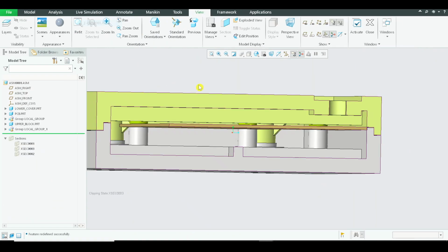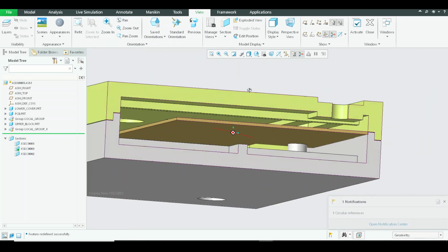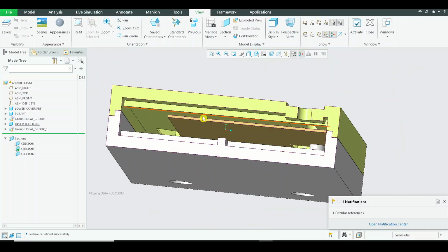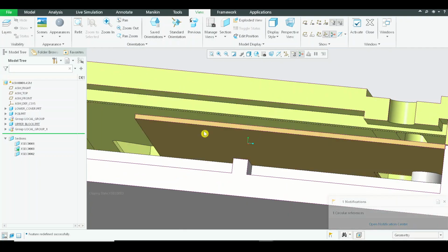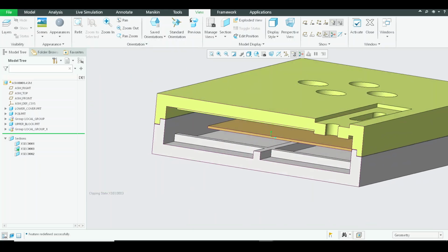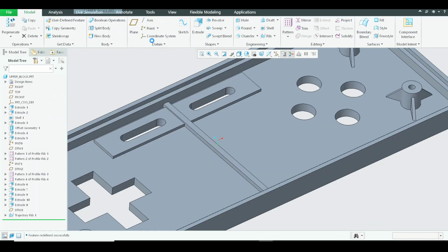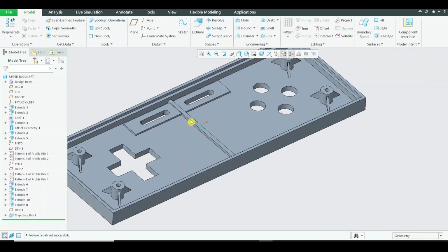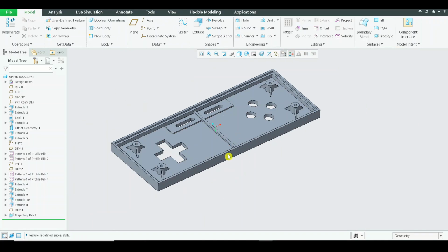Let us move back to the assembly and analyze. Yeah, there is sufficient distance. Again, if there are some blocks of parts which are interfering over here, then we can stop the rib at that location before that. Okay, so we can give gaps for that as well. That is not a big problem. What I'm meaning to say is we can just stop the rib from here to here itself. It depends on the positions of the PCB items as well.